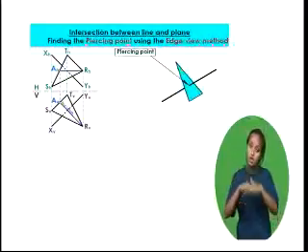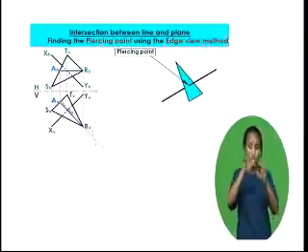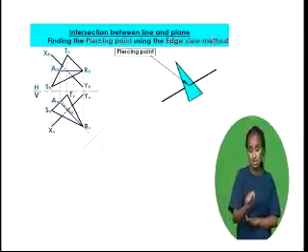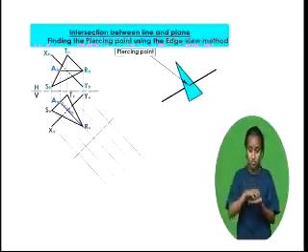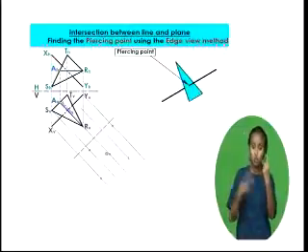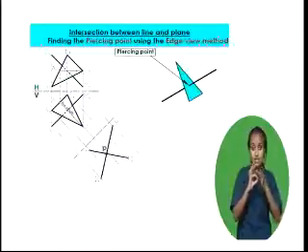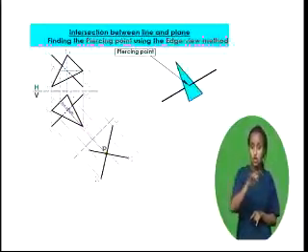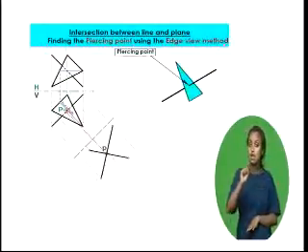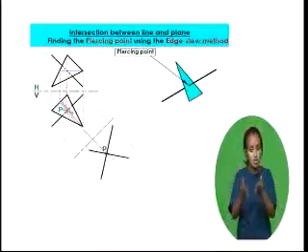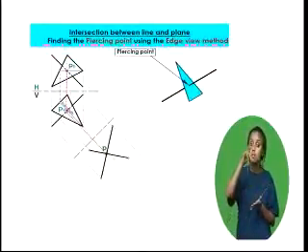Introduce an auxiliary projection plane 1 to find the edge view of plane RST and transfer distances from the horizontal projection plane to plane 1 using the concepts you have learned in chapter 3. The intersection point of line XV, YV with the edge view of the plane RV, SV, TV will give the piercing point PV. Project the piercing point to the other views.